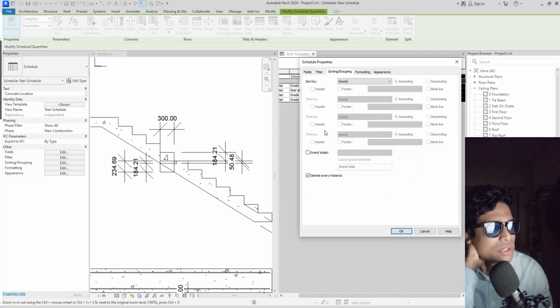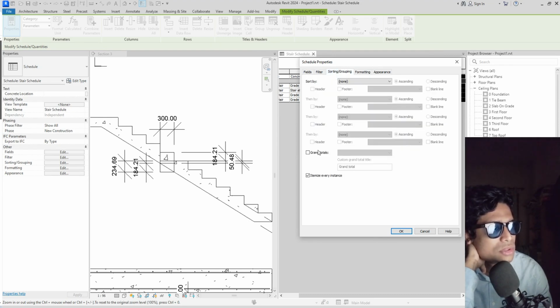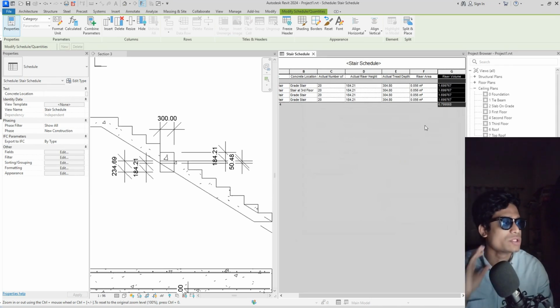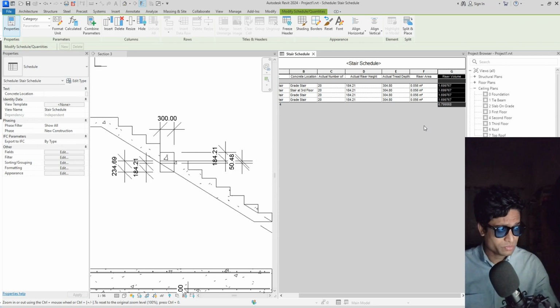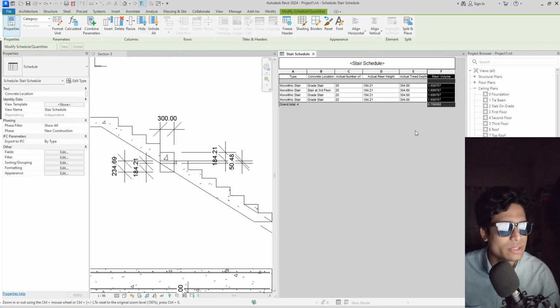and now let's find out the grand total riser volume. Calculate total. There's the grand total. Okay, so we need 6.799 cubic meters of concrete right here, and that column doesn't have any purpose, so why don't I hide it?